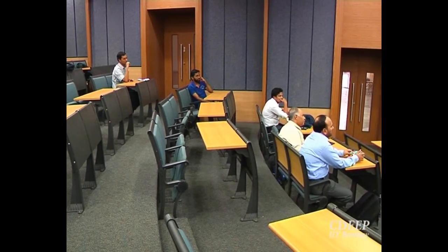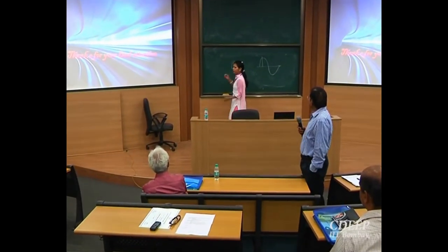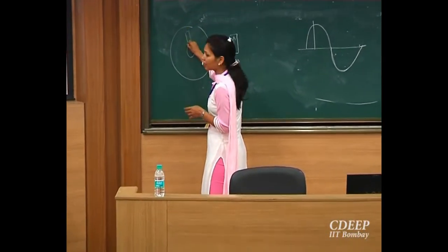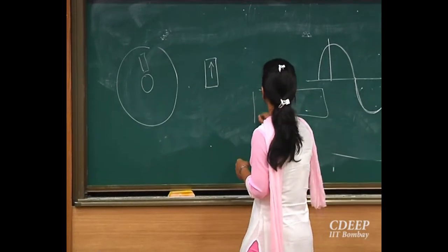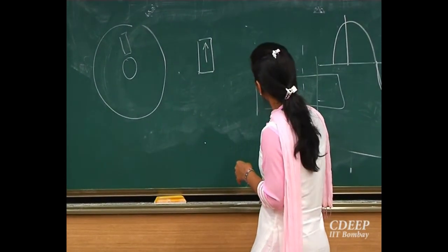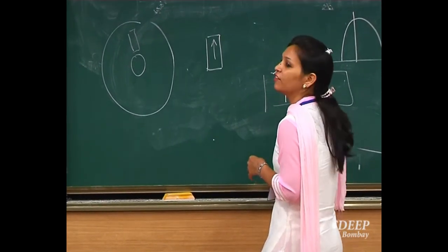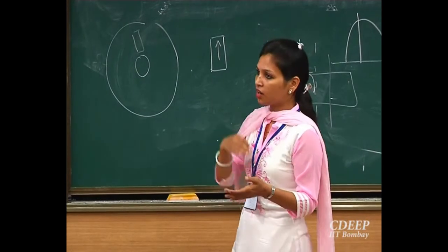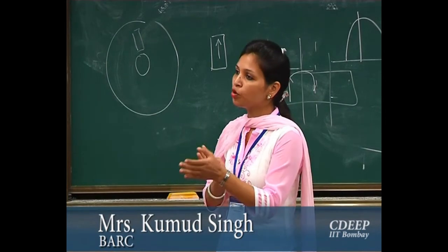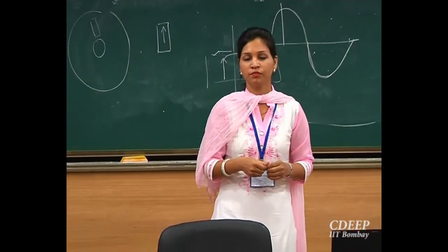By magnets. In the beam stick tube, we have taken axially magnetized magnets, created an aluminum sprocket, and arranged these axial magnets. If I see in this view, this is the beam line. These are the axially magnetized magnets. Here, all shapes we have tried to optimize so as to direct these field lines into the cavity. Similarly, in the miniature Klystron, magnets are on two sides. It's not 360 degrees, but we have still kept the pole shape optimized so the field inside the RF cavity is uniform.